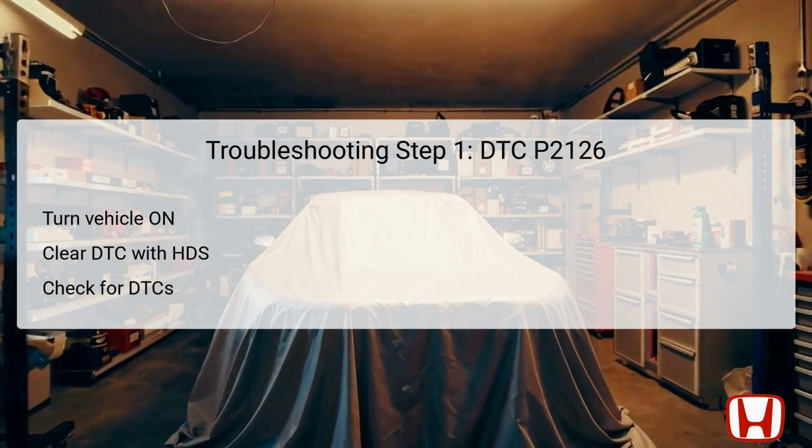The first troubleshooting step requires verifying the issue by engaging the vehicle in the on mode, ensuring that all systems are powered. Following this, the technician should clear the DTC using the Honda Diagnostic System, HDS, which is essential for resolving any intermittent issues that may have caused the trouble code. After clearing the DTC, wait for at least 10 seconds before rechecking for any pending or confirmed DTCs. If DTC P2126 reappears, it confirms the sensor issue, indicating the need for further investigation.